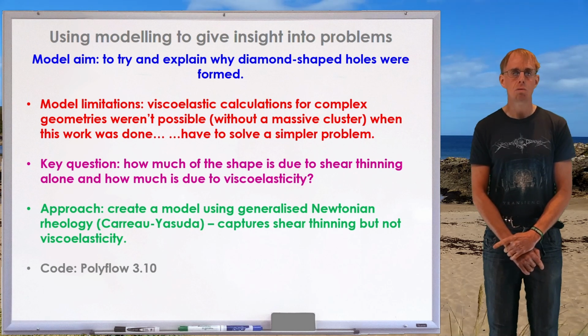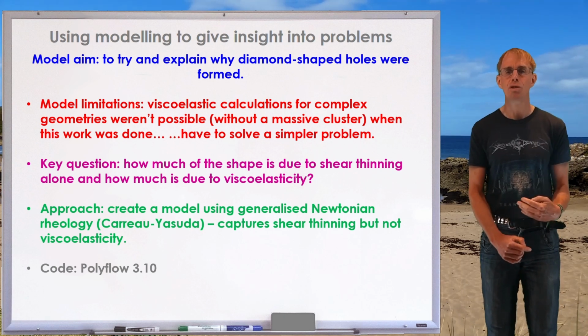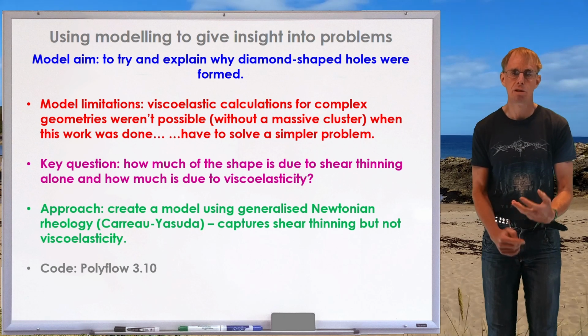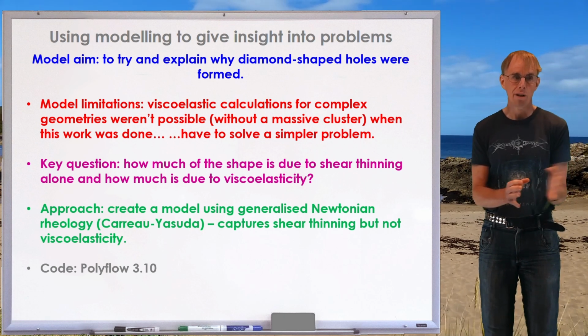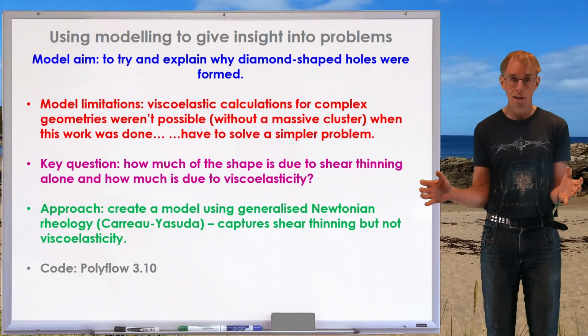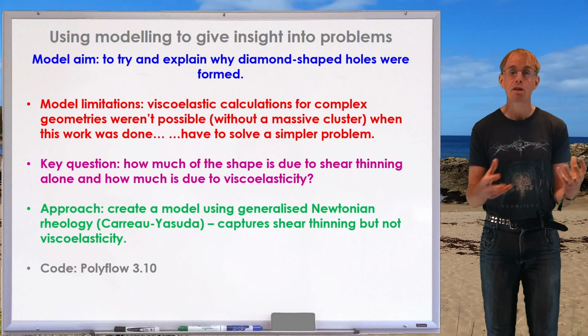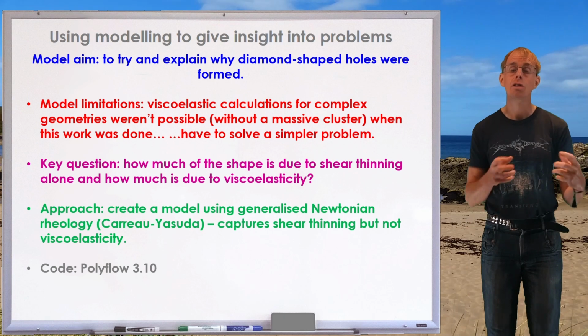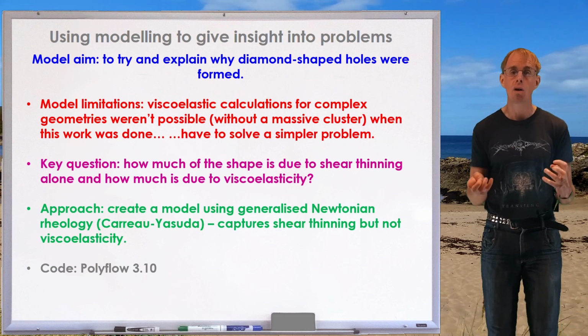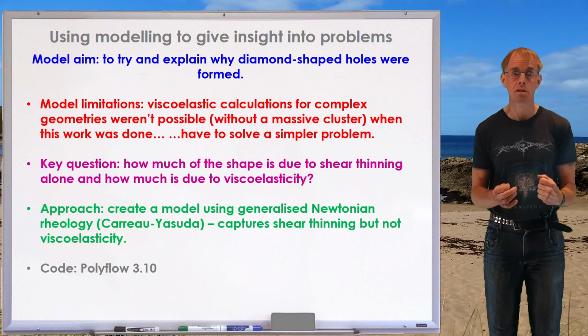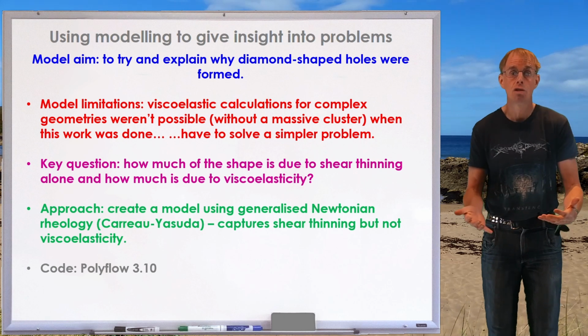And so effectively what Polyflow allowed us to do was to do a deformation calculation. You define a mesh that includes your die and your product, and you put some boundary conditions on it, and it'll figure out how that mesh deforms such that those boundary conditions are honoured. And the key boundary condition is what happens in atmosphere. There's no stress on the surface.